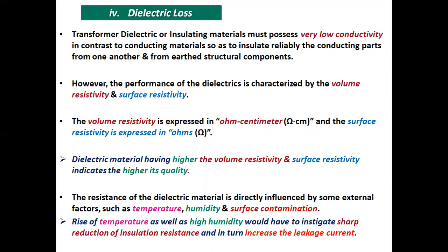The resistance of the dielectric material is directly influenced by some external factors, such as temperature, humidity, and surface contamination. A rise in temperature as well as high humidity would instigate a sharp reduction of insulation resistance and in turn increase the leakage current.